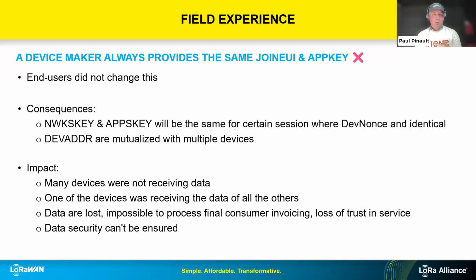But in a LoRa network, in fact, we can differentiate different devices sharing the same address thanks to the signature that is used with the NwkSKey. And so thanks to this, we can reuse the same DevAddr for a large number of devices. It depends on the capacity of your LNS to find the right device corresponding to this.